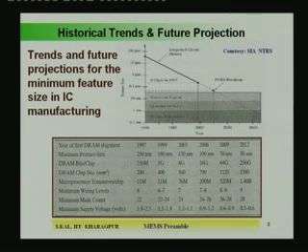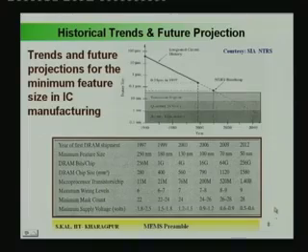So, if the number of levels of metallization increases, then automatically you have to compromise with some yield, but you have to make a compromise and get good yield, at the same time as the number of wiring levels increases. That is the motto and target, and mask count is going to increase if the levels are more. So, in interlevel metal you have to have a dielectric layer, then some metal pattern, then again another dielectric layer. So, automatically mask levels will also increase. So, that was the present scenario.